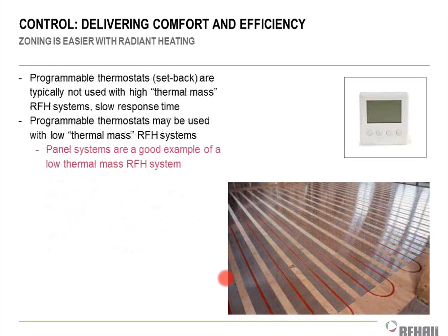We generally do not use programmable thermostats with radiant floors. And by generally, I mean don't ever do it. You are going to regret it. A lot of you have probably heard me preaching about needing programmable thermostats for code compliance. If you actually read the International Energy Conservation Code, you will see that there is an exception for these kinds of radiant systems, so you do not have to have the programmable stat.